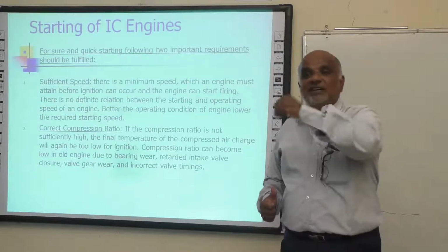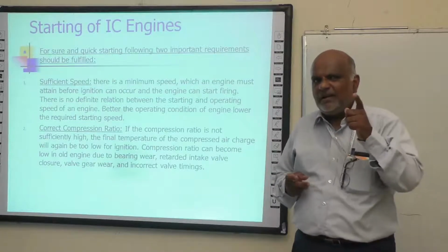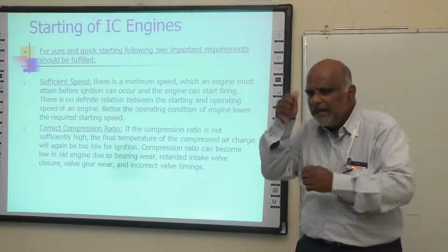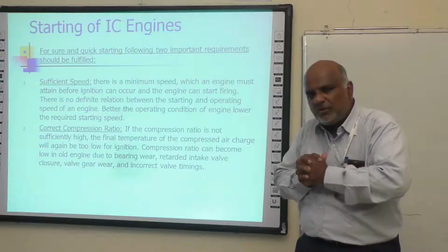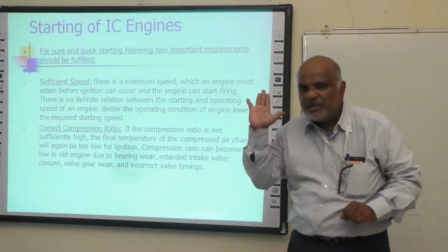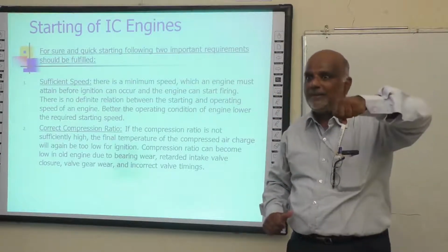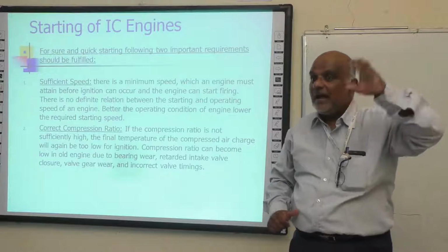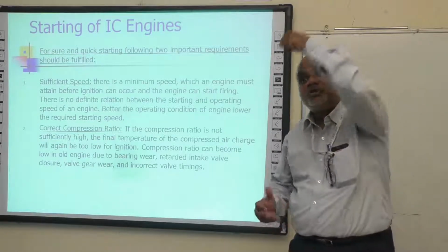Now, here the designers started developing a system. What was our thought? Make the piston move up and down. Why should you make the piston move up and down? To reach the spontaneous ignition temperature of the air. That is all the aim. What they did, they used compressed air at a pressure of 30 kg per centimeter square to push this piston down.